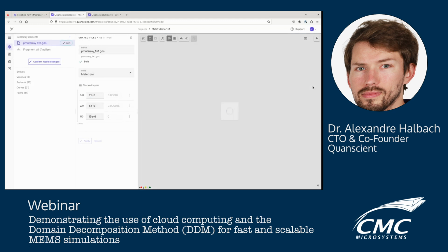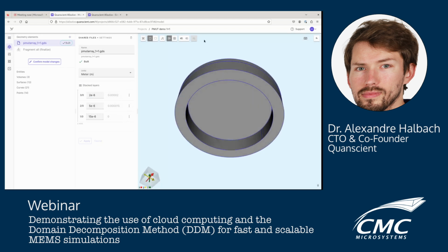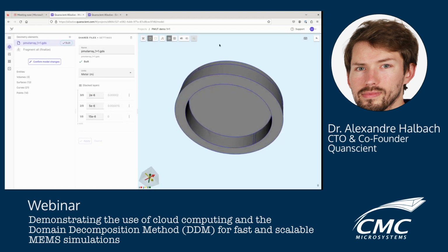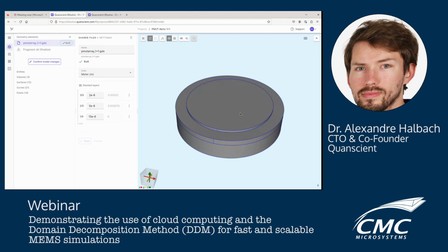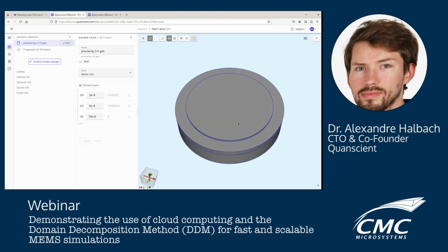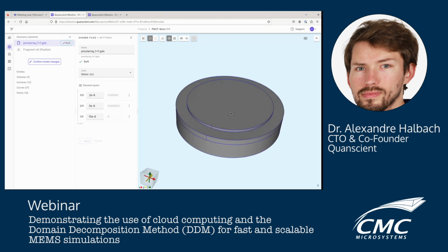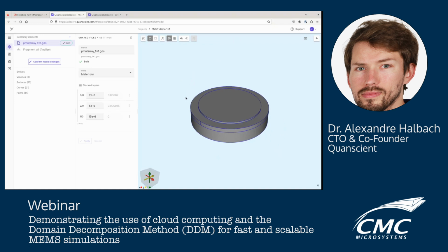We'll see how the PMUT looks. This is how the PMUT looks. So it's arguably not the most general and advanced model, but nevertheless, it has a membrane, a cavity, a piezoelectric layer, which I don't know in this case, but typically is best at 67% radius of the membrane, but this will do. And then what we need on top is, here we're not going to simulate the substrate elastic wave. The focus will be on the acoustics on top, but we can do both.